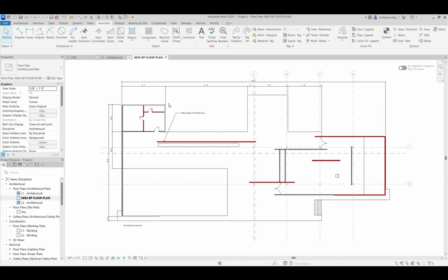All right, so we're almost done with the floor plan. I'm now going to show you how to create reference views. Reference views are section lines, elevation markers, that kind of thing. And for my students, I'm asking them to do 1 longitudinal section of the pavilion, 1 transverse section of the pavilion, and then all 4 elevations. So let's set that up.